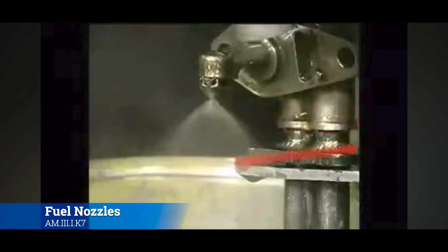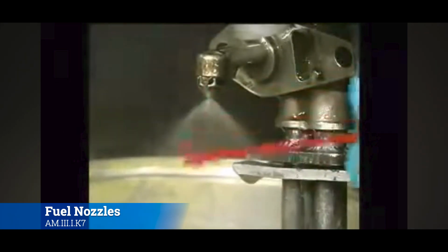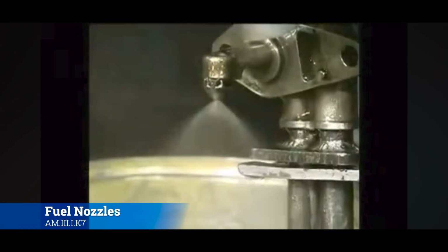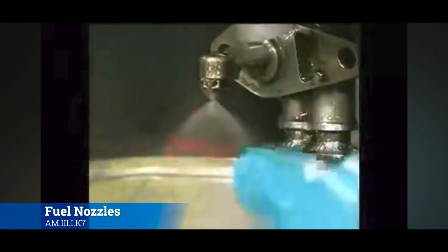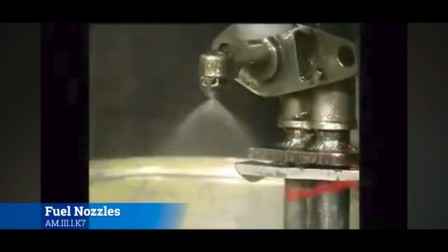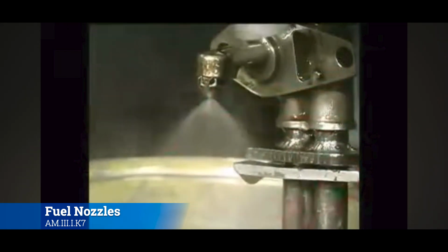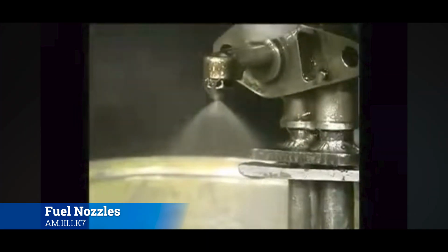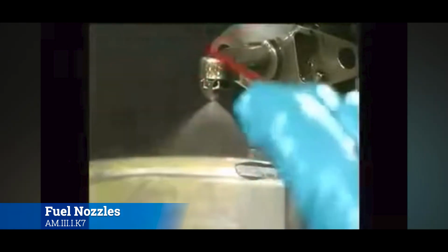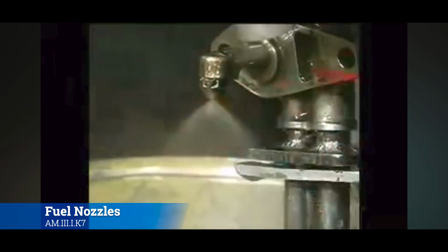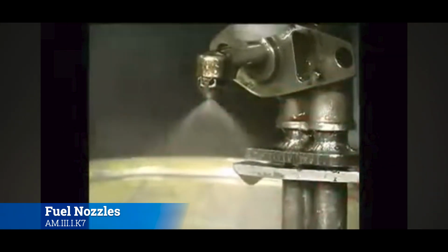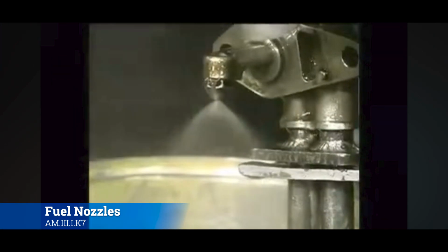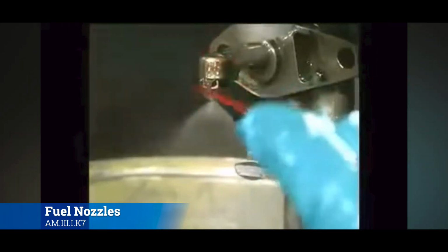So the fuel nozzle spray check is probably one of the most important parts you're going to do on an engine 100 hour. You're going to make sure that the fuel is moving correctly through the spray nozzle, and that there are no non-conformances in the nozzle itself, in the spray pattern, that then could lead to much bigger problems later on. Changing a nozzle out is not really that big of a deal. Cleaning a nozzle, not really that big of a deal if it's allowed. But the main thing that you want to avoid is having to do maintenance that could have otherwise been prevented through simply checking the spray pattern.